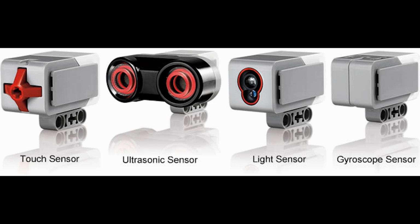The light sensor allows the robot to see colors. It can tell the difference between many basic colors such as red, green, blue, white, and black. You can program the robot to move faster or slower when it detects or doesn't detect the color you specified. The gyroscope sensor allows the robot to know which direction it's going. You can use the sensor to tell the robot to go a certain degree for a certain amount of time.